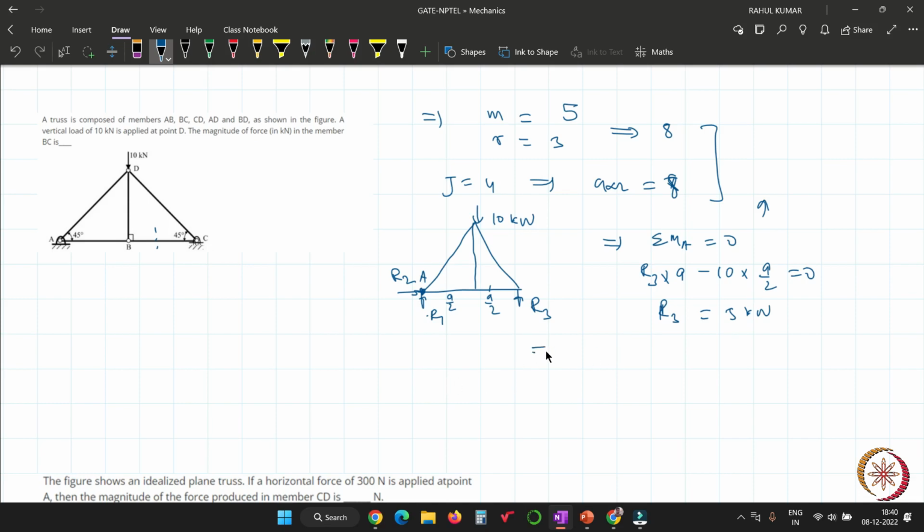Now I have to determine the force in this member. If you want to skip finding R1 and R2, you are still able to solve this problem, because there is no need to find R1 and R2. So I skip the other equilibrium equation, and then I create the FBD of joint C. Suppose the force in member CD is P1.